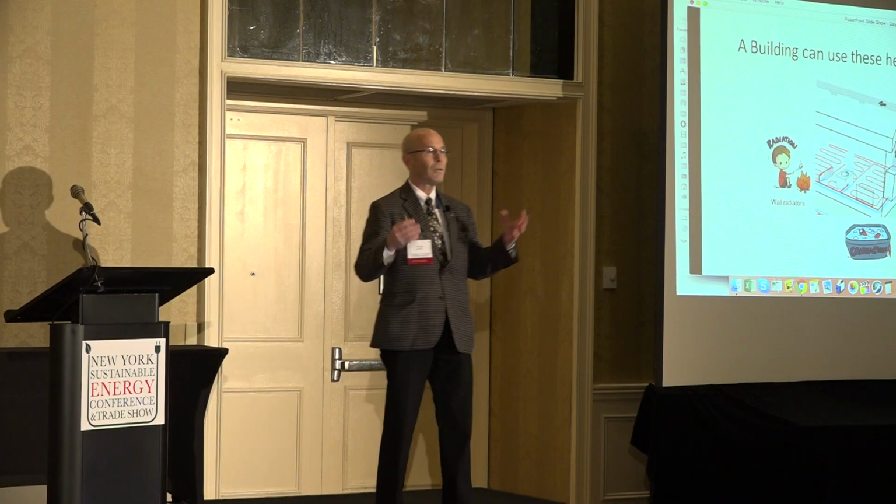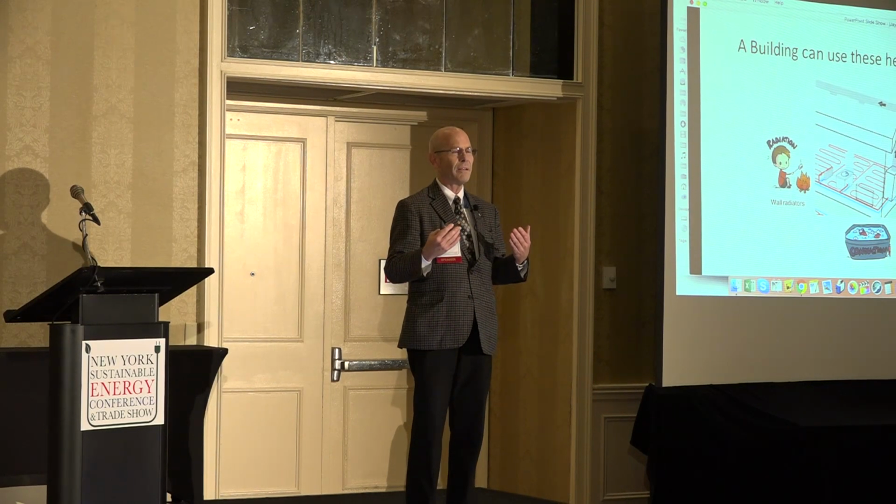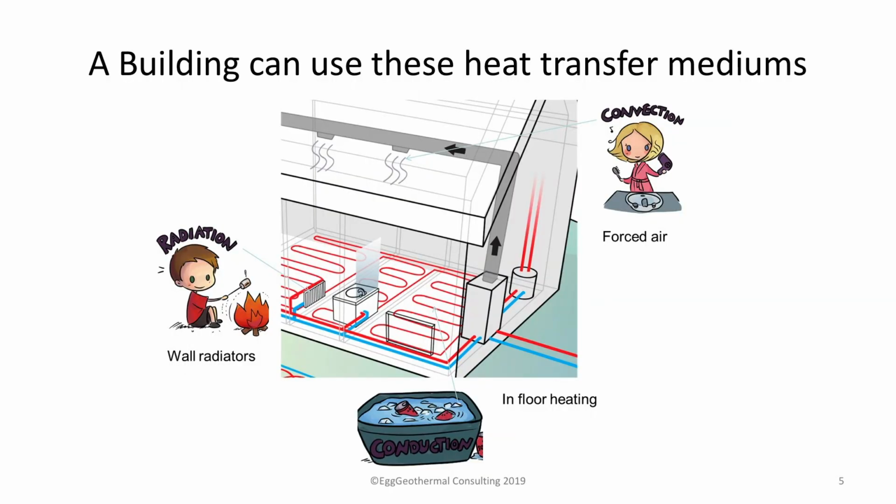Radiation is what you feel. Everybody has seen a radiator. If you stand in the vicinity of it, you get electromagnetic waves that turn into heat energy when they hit a solid object. You have convection, which is forced air, the bulk movement of molecules through a duct system. It's either heating or cooling. And then you have conduction. That is when you would be able to slip your shoes off and you have a conductive radiant floor and it feels warm to the touch. You can feel that and it feels comfortable. And that also doubles as a radiation source.